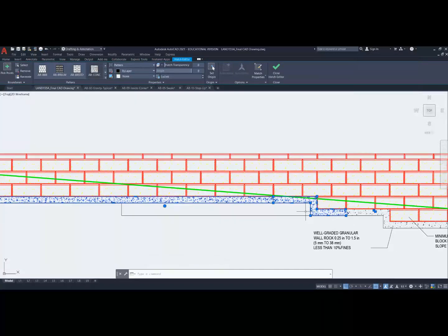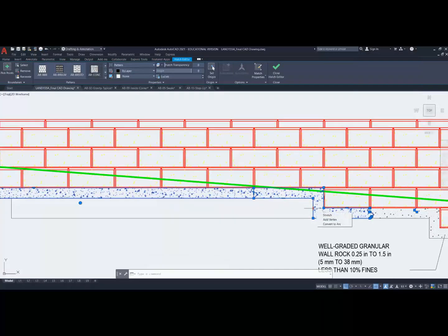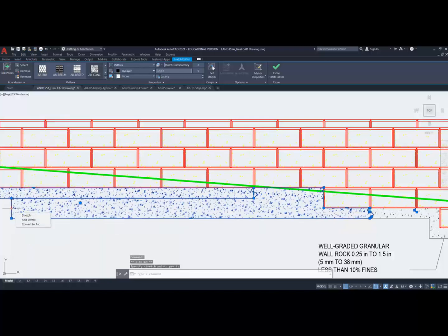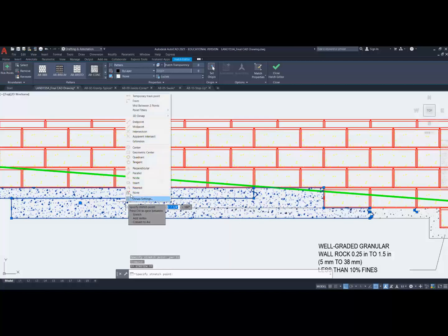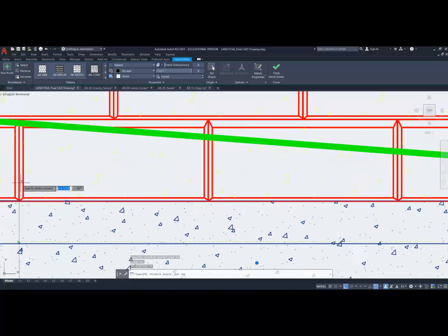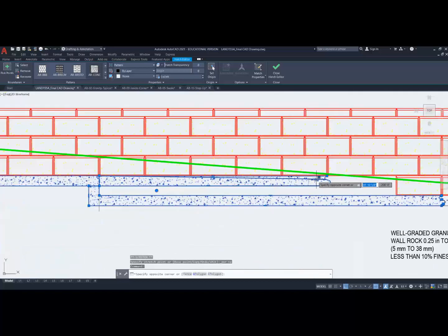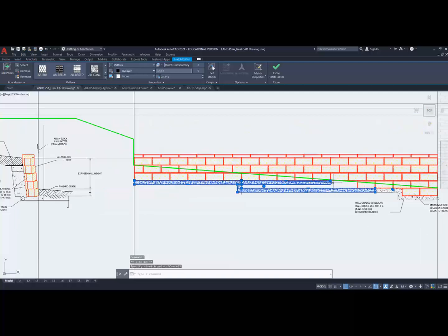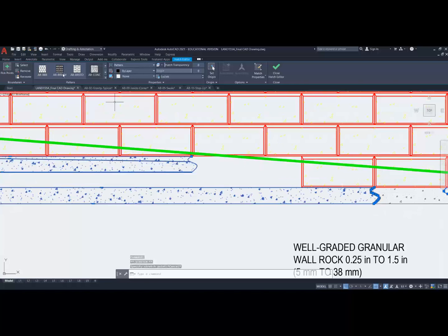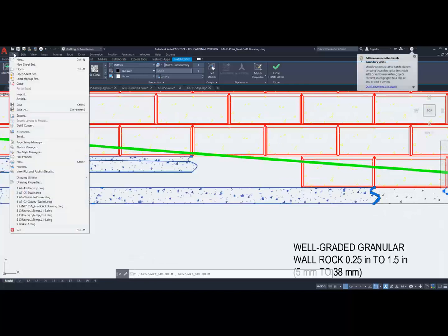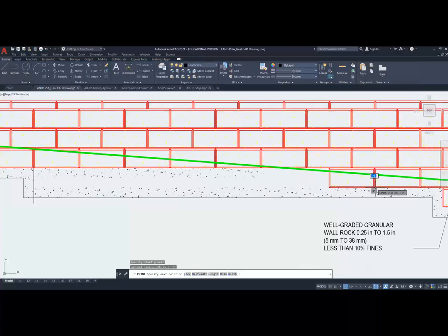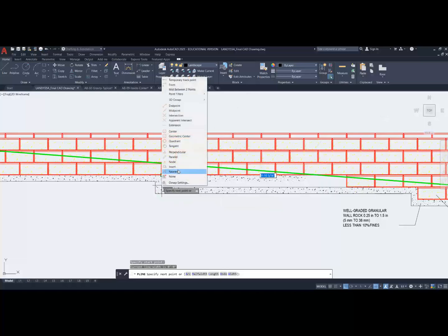Now, this is not a big thing because I'm just going to take the hatch and move it perpendicular to here. And I'm going to take that hatch here and move that perpendicular to that middle line here. Wow, I got a lot of stuff going on with their hatches. So what's the best solution here? I'm going to forget theirs. I'll go into Home, and I'm going to create a polyline. It's a temporary line, and I'll create it from there down to the line I created.